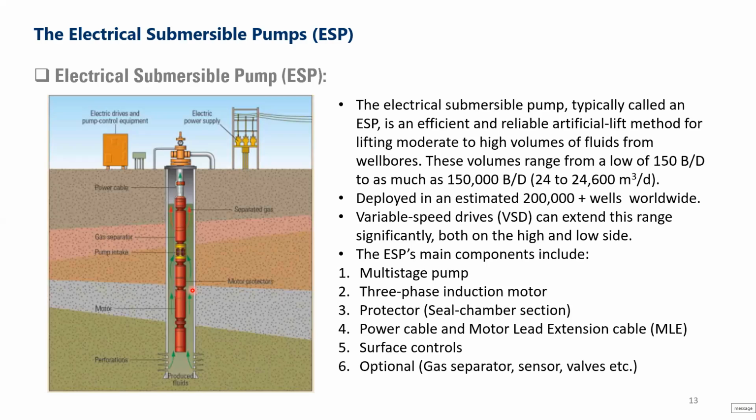So the protectors use the mechanism of difference in fluid density. The chambers in the protectors are filled with oil. Whenever we have the intake, which is right above the protector, the oil will go from the intake. Some of this oil will go into the protector, and this oil coming from the reservoir has solids and some water content.